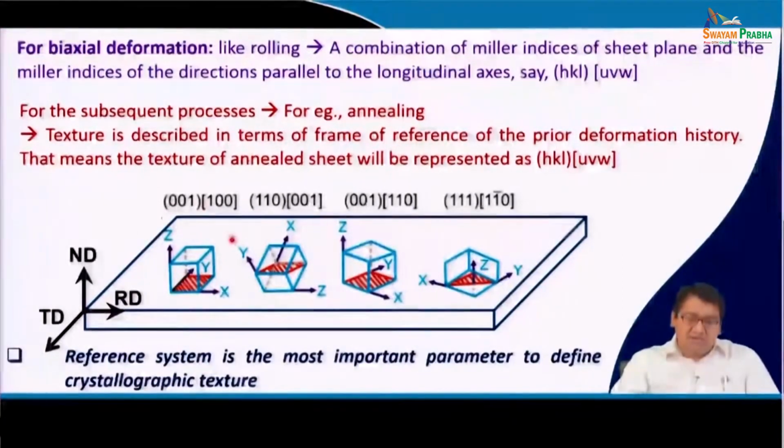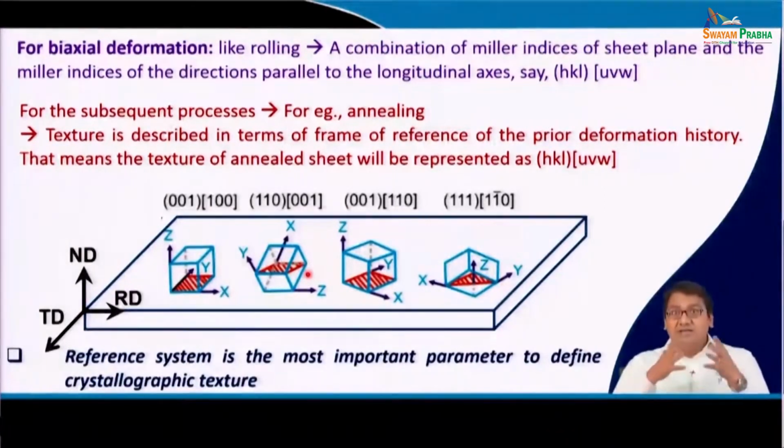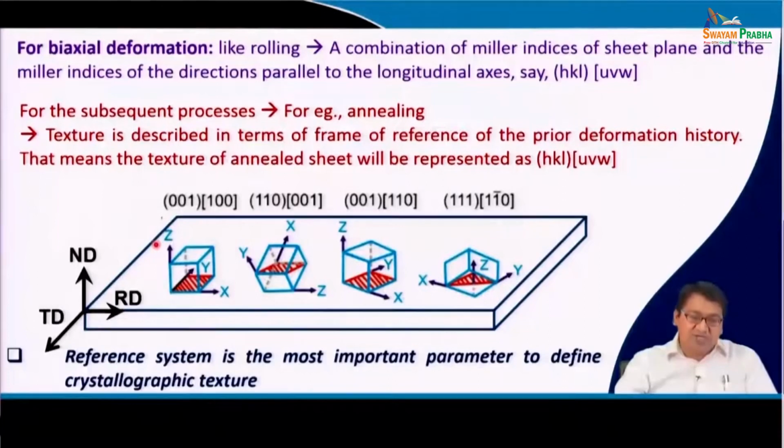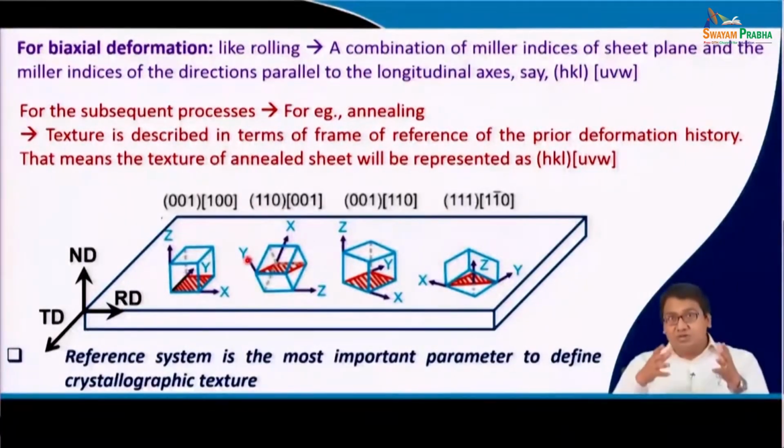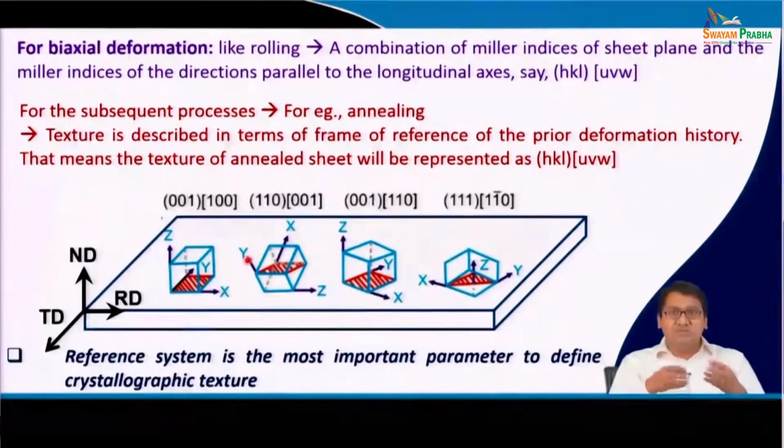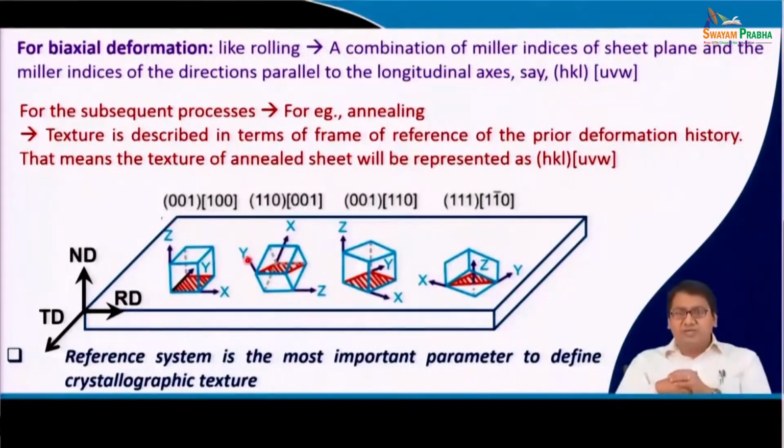On the other hand, other mechanisms like deformation, dynamic recrystallization, and even the cooling process and temperature lead to the formation of this kind of orientation, and we know that this is known as the cube texture orientation, that is 001, 110. On the other hand, this kind of orientation is basically the Gauss orientation, 110, 001, and a few slides back we came to know the names of these.